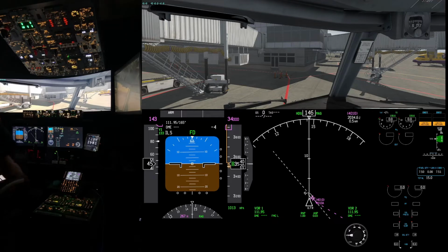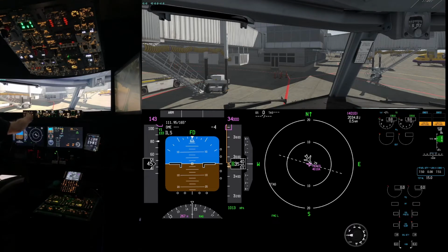Now that the flight plan is entered, I can check the route that is programmed into the flight management computer by looking at the map and making sure I don't have any discontinuities between takeoff and landing. So I turn the EFIS to plan mode, and then the FMC changes so that I can step through the flight plan on the screen.